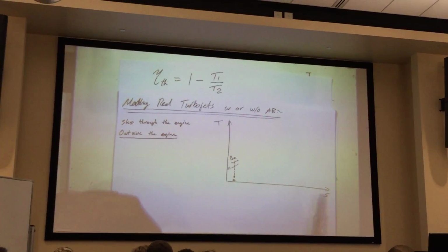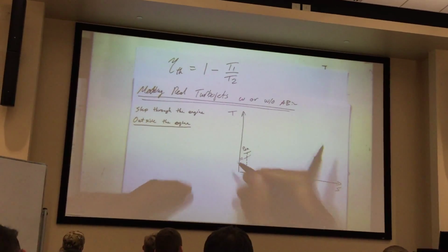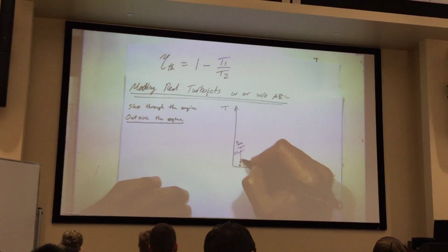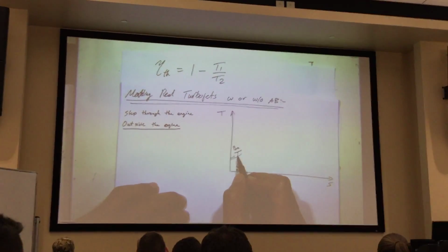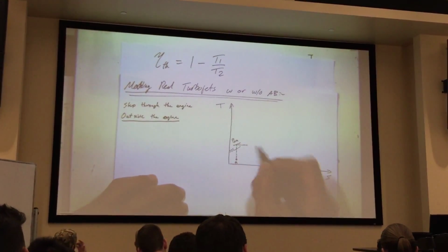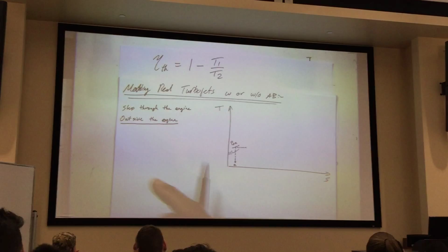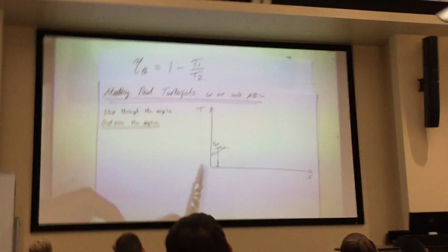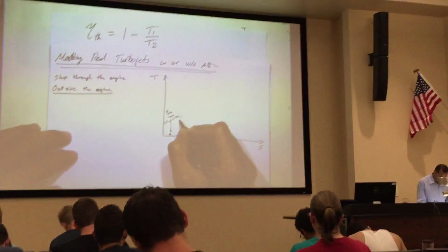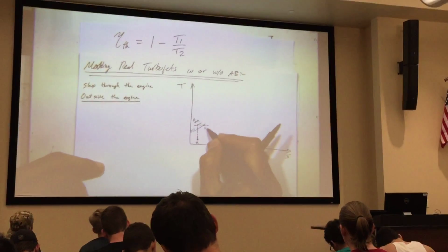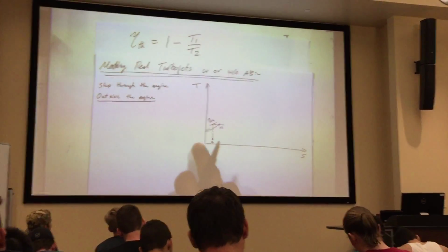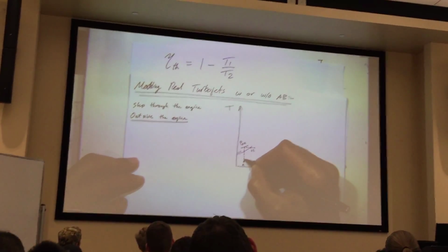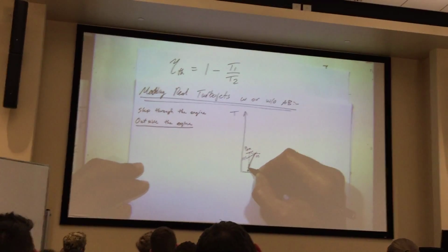PO2, which is primarily my isentropic ideal situation for PO2, but the real engine is going to be at that same temperature level as POA, but along this curve. So right there. So that's my PO2 actual. So this is the isentropic situation I raised up to here, but no, I actually end up there. So my curve ends up being this for the inlet.